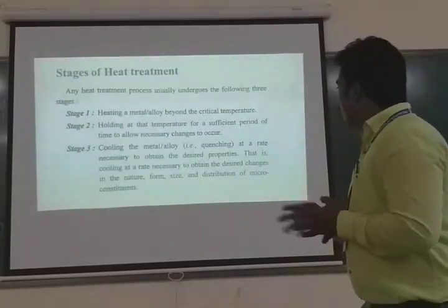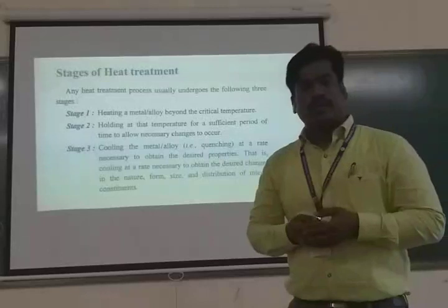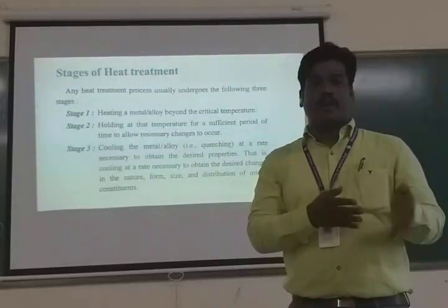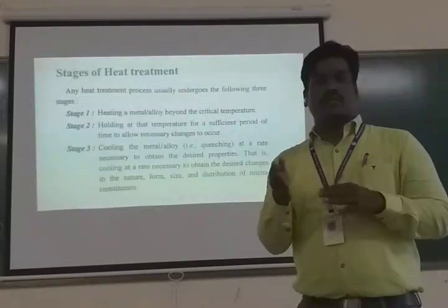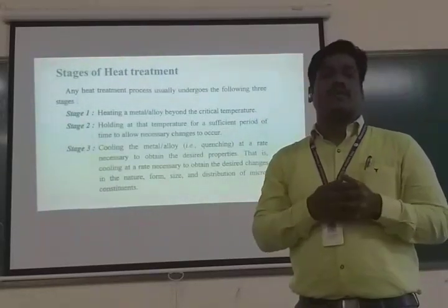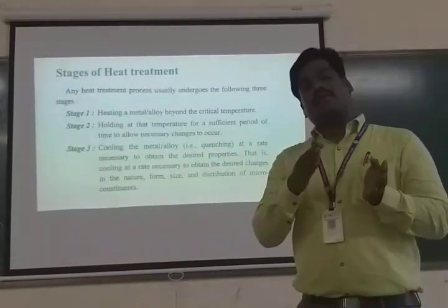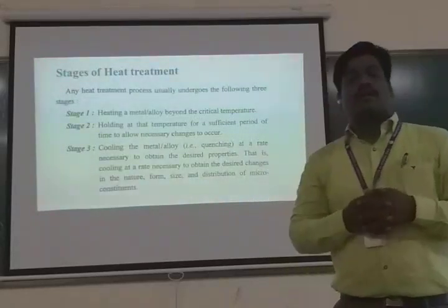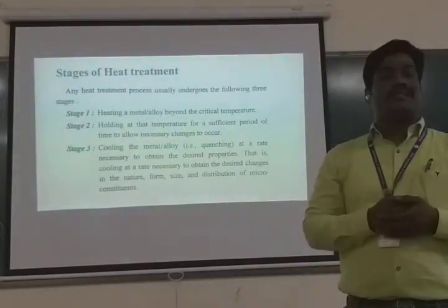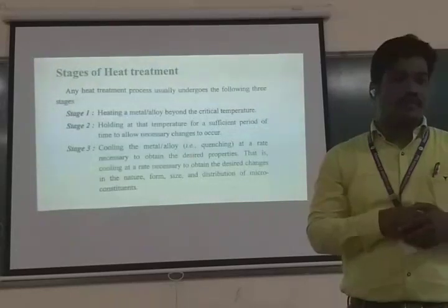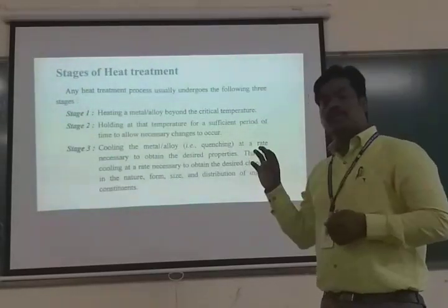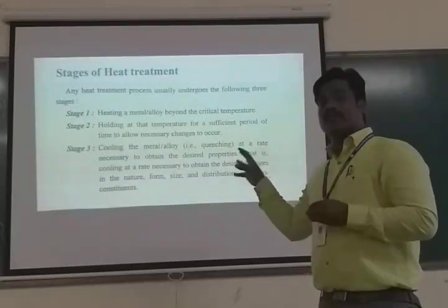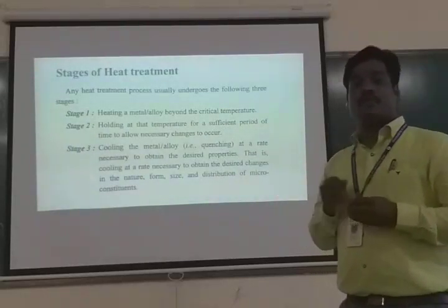If we use oil, the properties will be changed a little bit and the martensite will form more slowly. With the air cooling method, the material will be less hard compared to the water cooling method. So a lot of variations are available depending on the medium we use for finishing.